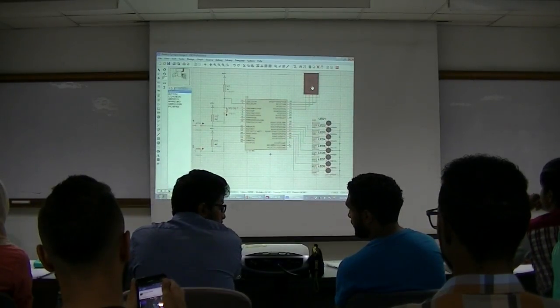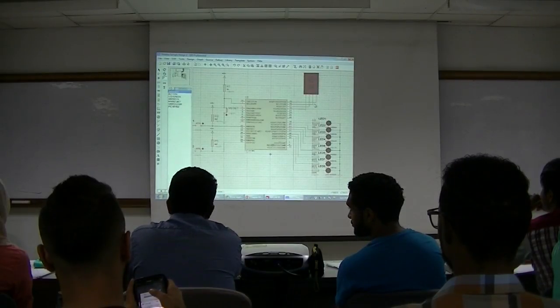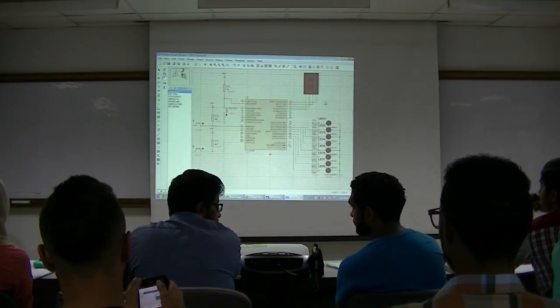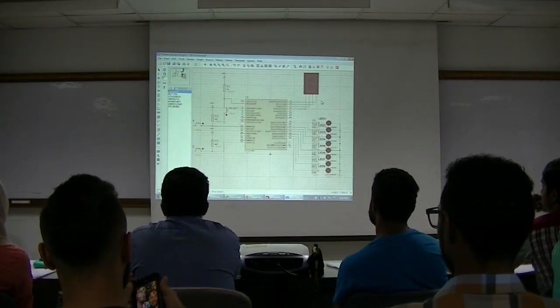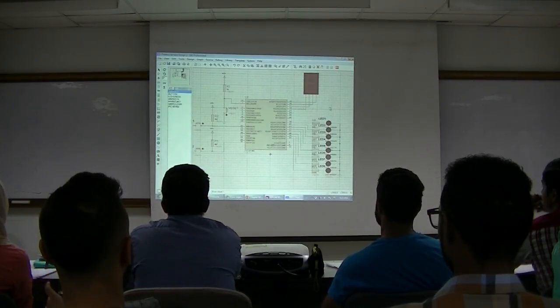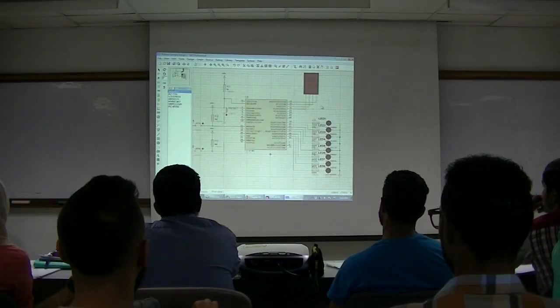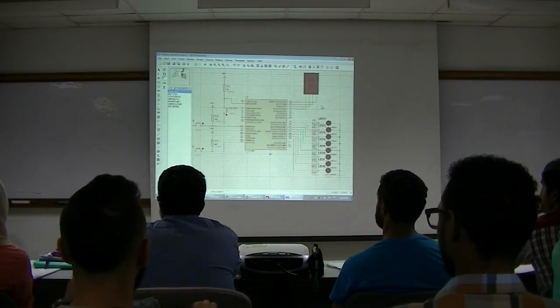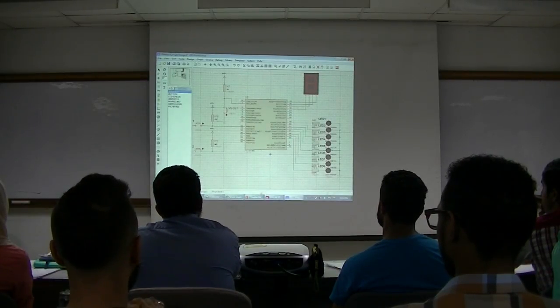Whenever this is a 7 segment, of course here the 7 segment you see is without a buffer IC. Take note that because this is a simulation, but in actual reality you need a buffer. You cannot connect straight like this. Can, but it will be very dim. You get the idea?